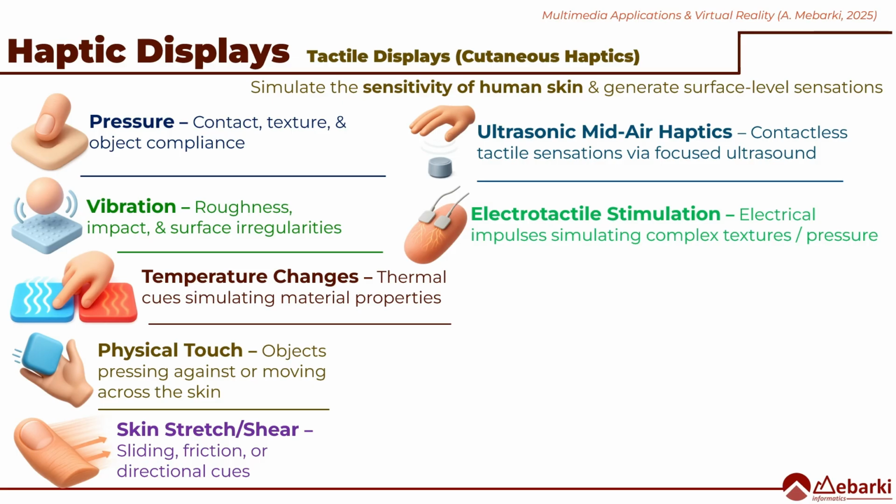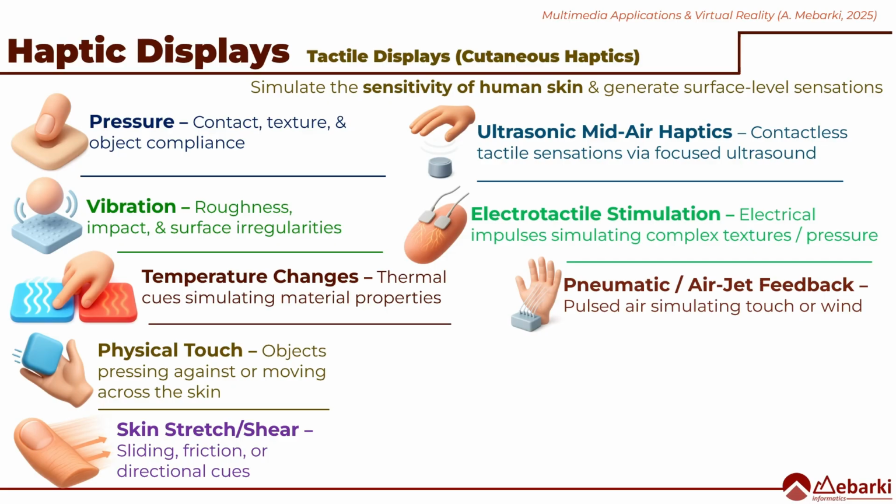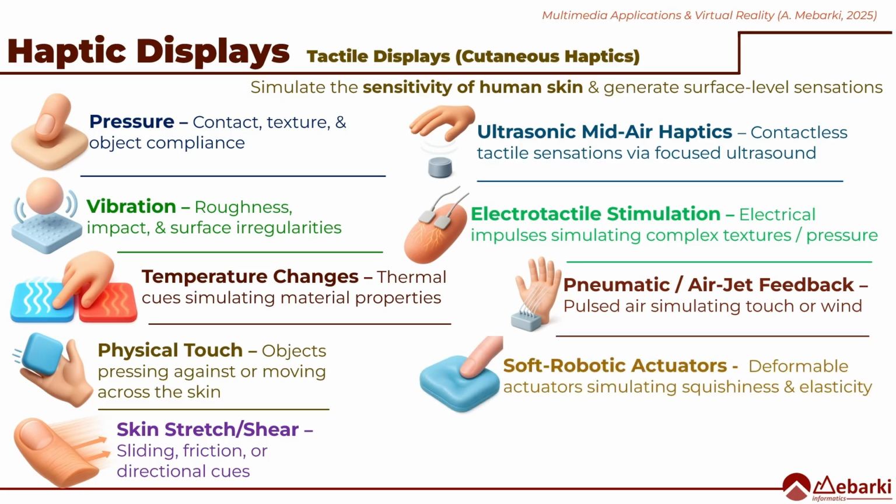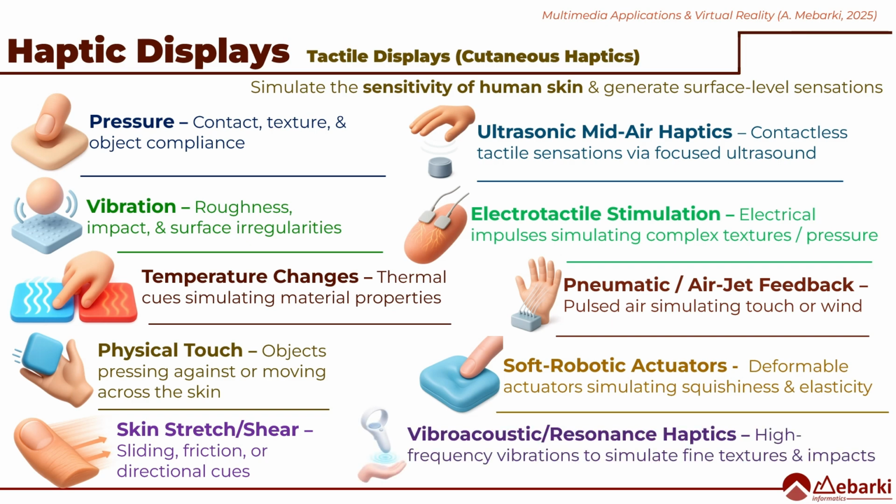Additional approaches include pneumatic or air jet feedback, where pulsed air simulates touch or airflow, and soft robotic actuators which deform to convey squishiness and elasticity. Finally, vibroacoustic or resonance-based haptics rely on high-frequency vibrations to reproduce fine textures and sharp impacts, further enriching tactile interaction in virtual reality.